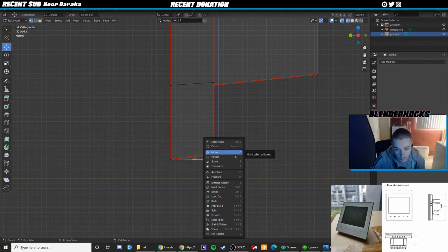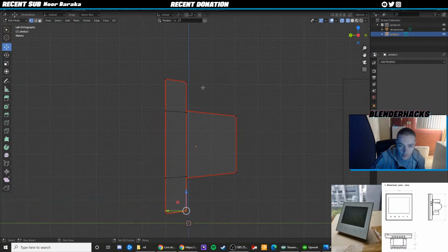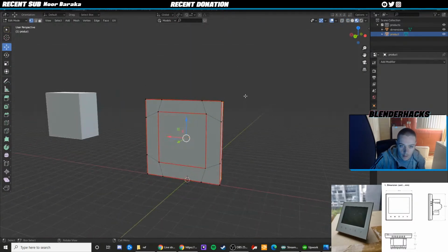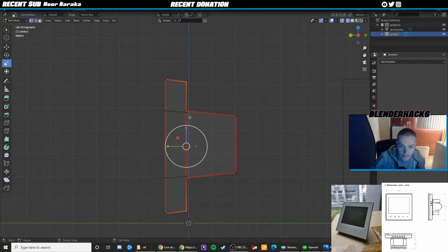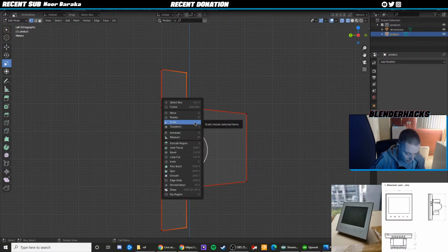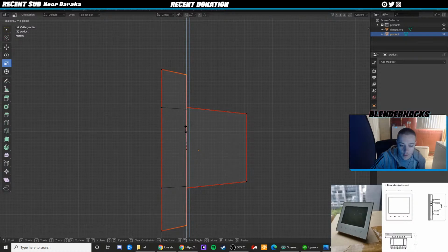So Shift plus brings up this menu, and then G for move, R for rotate, S for scale, T for transform. So it's usually always G, R, or S. So I want to set all these. I've just realized this is before I added... shift space, scale, shift space, S. And then you can scale it down holding shift to reduce the speed. So without shift is this, with shift is this, and we'll go down a bit.